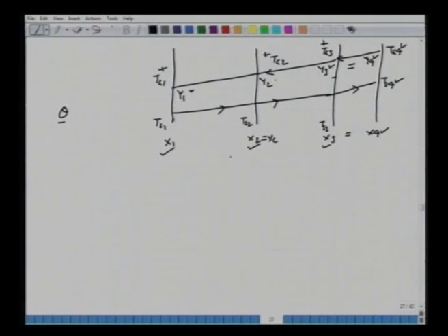All right. So in this case, when we want to calculate the enthalpy, how do we calculate the solid enthalpy at any location between 1 and 4? Hs will be equal to CPS, the specific heat of the solid. If we choose 1 kg, or 1 unit weight, of the solid, it will contain X amount of moisture. So we have CPW, since 1 kg contains X kg. That's the moisture content. Times Ts, the solid temperature at any location here, minus some reference temperature T. Generally, you can choose the reference temperature as 0. There's no harm in this, as long as we are consistent.